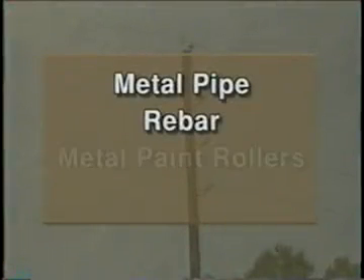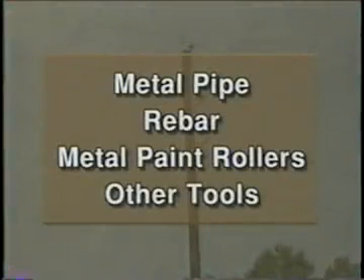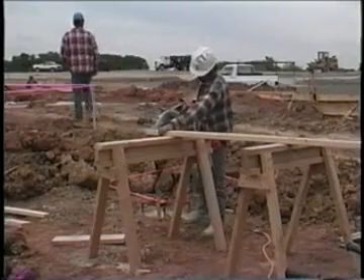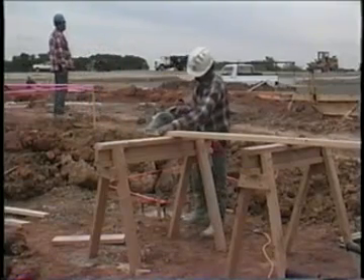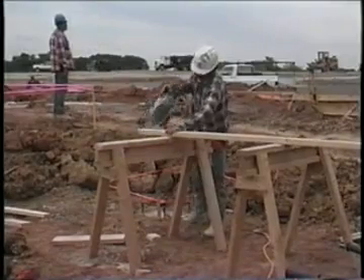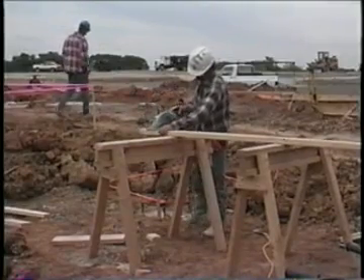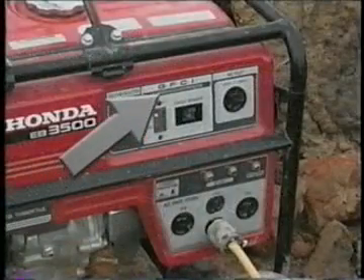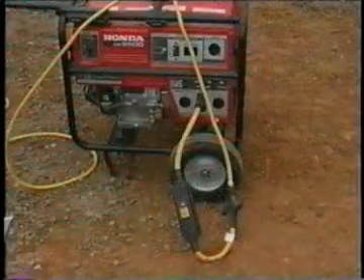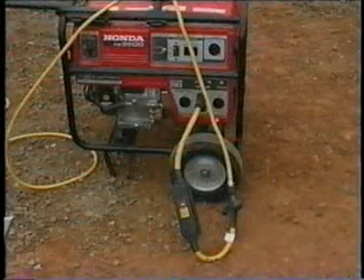Many other fatal electric shocks on job sites were due to contacting energized conductors while holding metal pipe, rebar, metal paint rollers, and other conductive tools. About 5% of fatal electric shocks on construction sites were due to ungrounded tools. Strict adherence to the Assured Equipment Grounding Conductor program required by OSHA and 100% use of ground fault circuit interrupters on electrical extension cords can totally eliminate this type of accident.